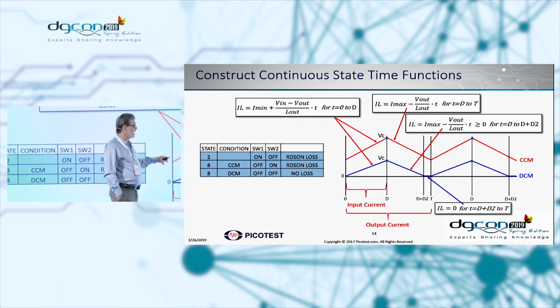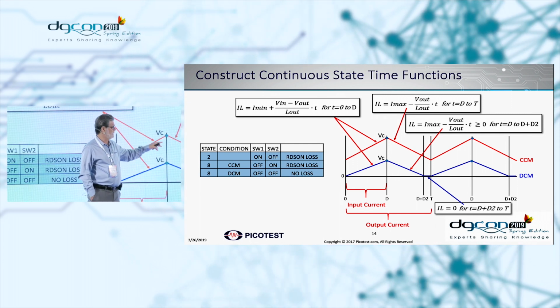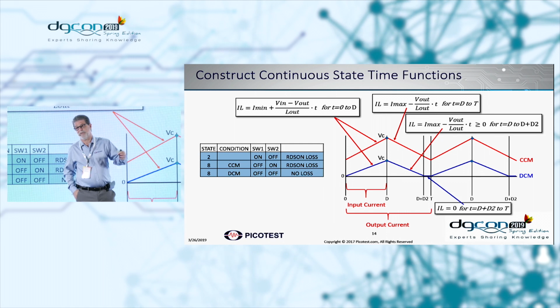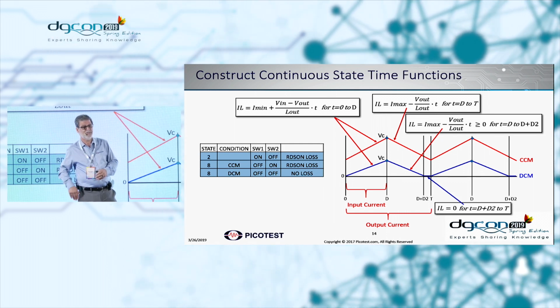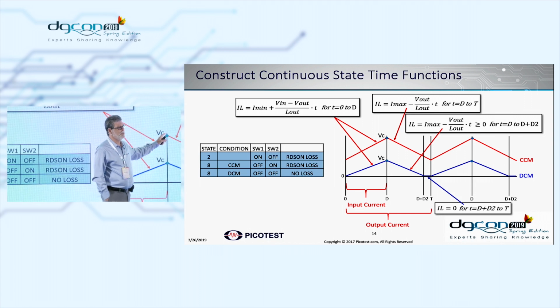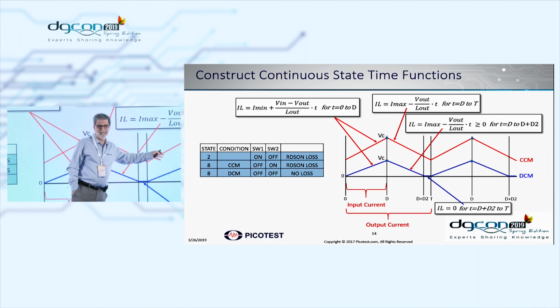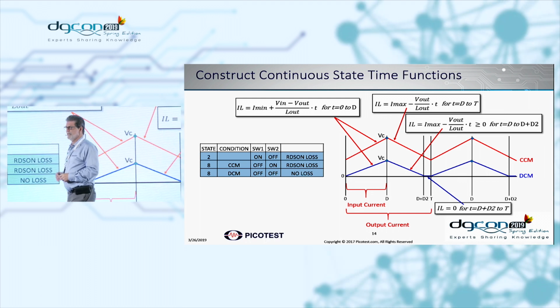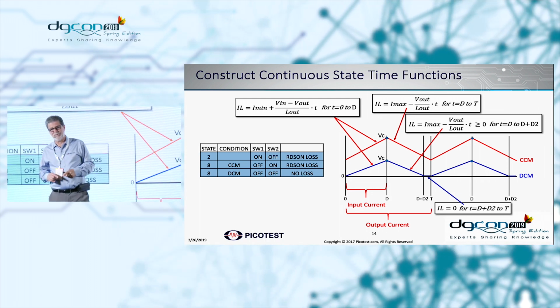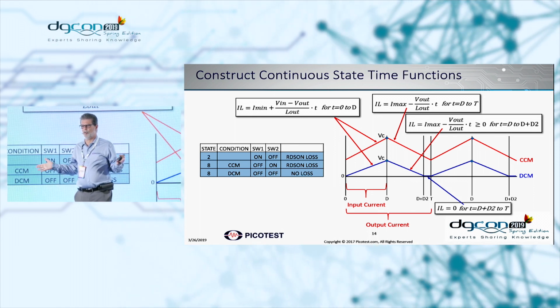So we started a cycle right here. The inductor current ramps up until that point is satisfied, where the control voltage is equal to the sum of the ramp and the current signal, and we terminate the cycle. Once we terminate the cycle, the current starts to fall. Of course, we can calculate the slopes of those rises and falls because the inductor is connected either to the input voltage, the output voltage, or ground.